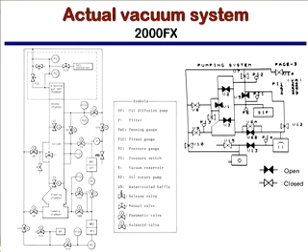What you want to do is go through and figure out, okay, what pumps are where? Okay, so we have DP, a diffusion pump here, diffusion pump 1, diffusion pump 2. RP, roughing pump. There are different gauges, the Penning gauges, the Pirani gauges. There's the vacuum reservoir, the oil rotary pump, all the different things. And then there are these little bow tie looking things, which are usually the way that we describe the valves, and it'll tell you what is considered open and what is considered closed, whether or not this is full or empty.